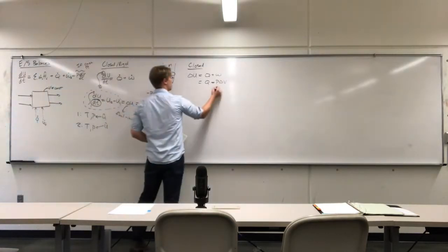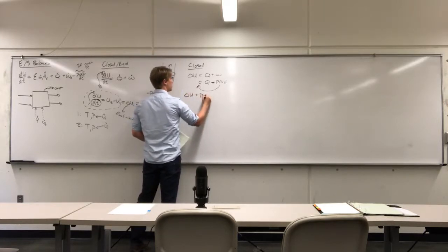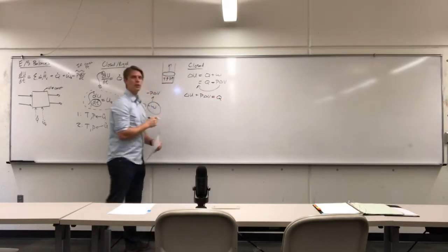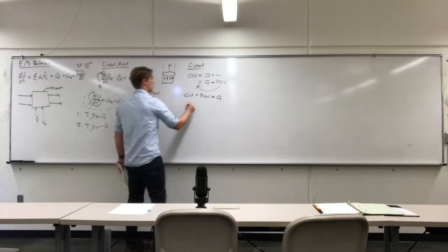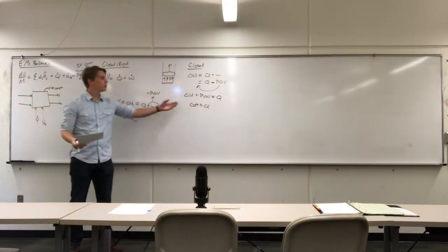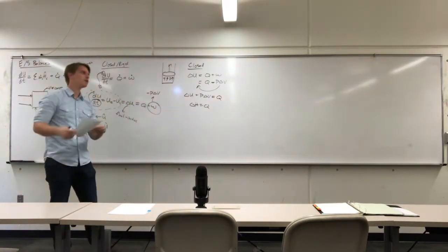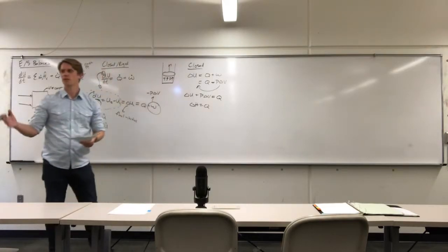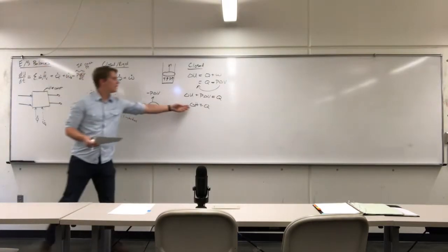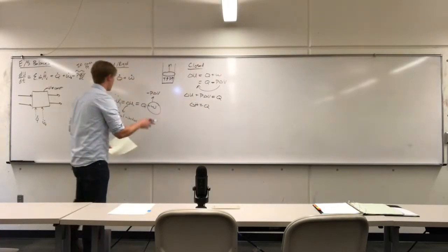What we'll oftentimes do is we'll move this to the other side of the equation. So we have the change in internal energy plus the change in PV is equal to the heat required to accomplish the process. Then we'll oftentimes just do this. So even though it's a closed system, you still are using enthalpy. That's why I don't want people to think, oh, it's closed, that means you use internal energy, oh, it's open, that means you use enthalpy. It's all just a consequence of the energy balances. So enthalpy is useful in more ways than just for open systems. That's sort of my last pitch on that.